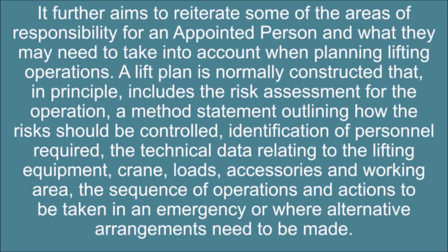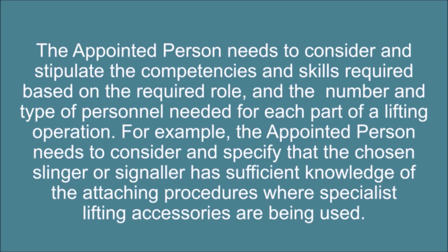A lift plan is normally constructed that, in principle, includes the risk assessment for the operation, a method statement outlining how the risks should be controlled, identification of personnel required, the technical data relating to the lifting equipment, crane, loads, accessories, and working area, the sequence of operations and actions to be taken in an emergency or where alternative arrangements need to be made. The appointed person needs to consider and stipulate the competencies and skills required based on the required role, and the number and type of personnel needed for each part of a lifting operation.